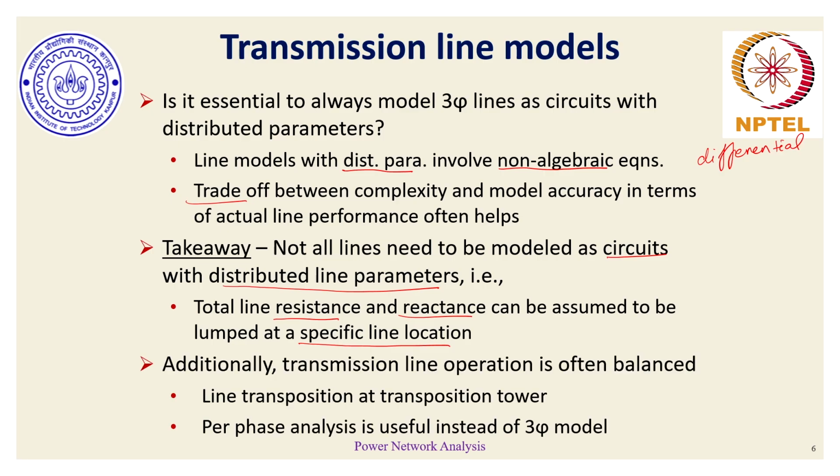And given that trade-off of how we want to model our transmission line, the line could have lumped parameters also. Again, lumped parameter is not an actual representation. It is coming in from the perspective of the trade-off required between complexity of the model and the accuracy of the solution behind defining the transmission line performance.